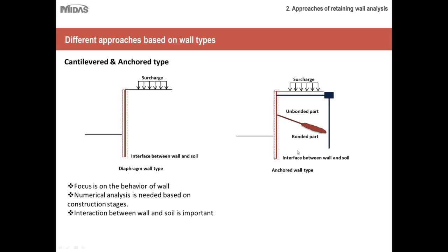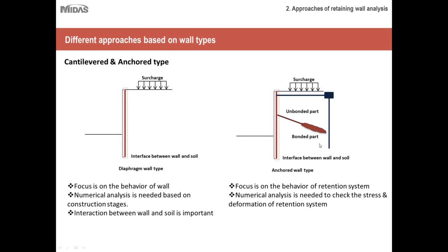So depending upon what type of retention system you are using, you should model that accordingly. But from this slide I want you to understand that for anchored wall type, the prime focus is not on the wall alone, it is on the retention system that you are using. And therefore numerical analysis is needed to check the stress and the deformation in this retention system.